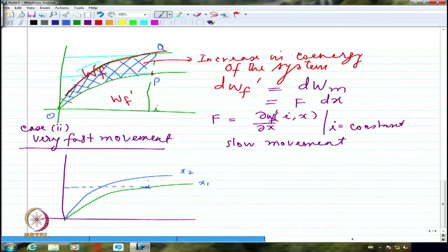Please understand that generally the cause is I and the effect is lambda. Cause is I and the effect is flux. And it takes a little while for the flux to show up the change in the current. If there is a change in the current, you are going to have a little bit of time lag before it shows up as a change in the flux. That's why we call it hysteresis. Hysteresis means lagging behind. The flux change always lags behind the current. So it's going to take a little while.